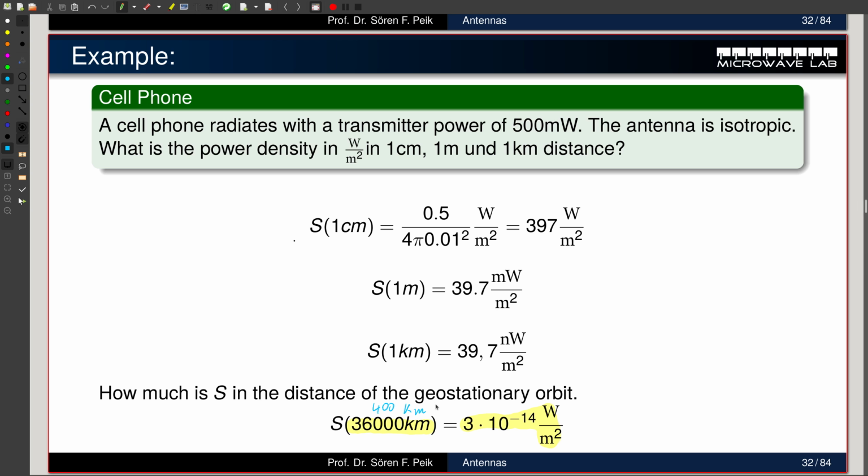Or we only transmit very little data. Remember, when we have very little data to transmit, very small power is acceptable. And that's something, for example, we get in GPS satellites. In GPS satellites, you only transmit a timestamp, which has maybe 5 bytes. And this timestamp is such a small amount of data that we can handle these small amounts of power. At a GPS receiver, the power is actually much less than the 3 femtowatts. It's less than a femtowatt. But it still works because we handle only a few bytes per second. That's all. Good.